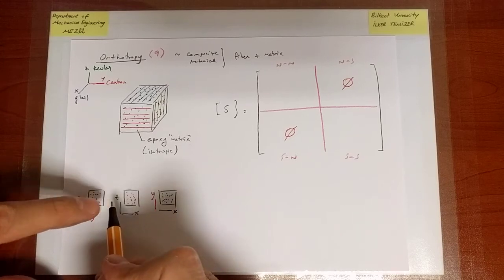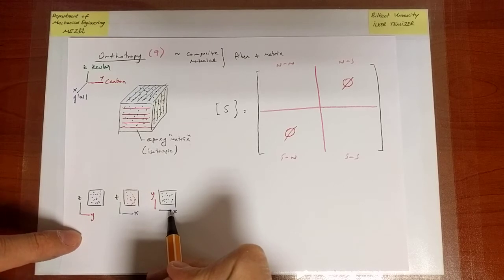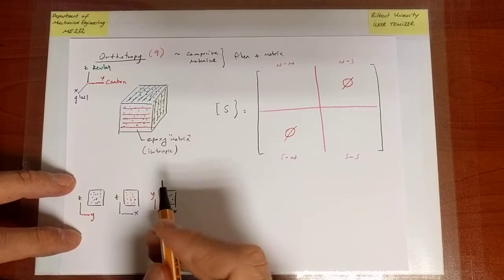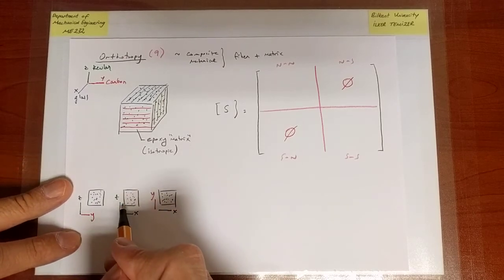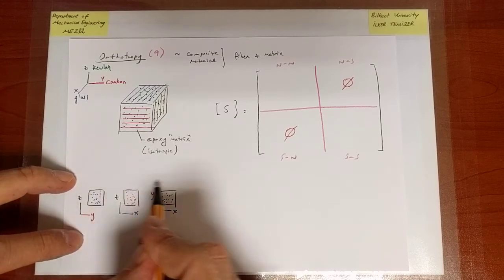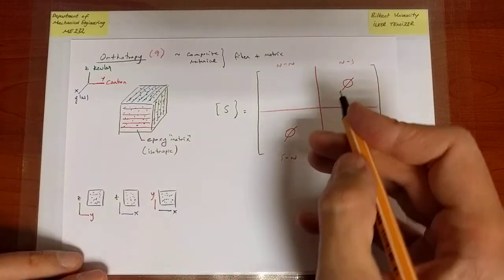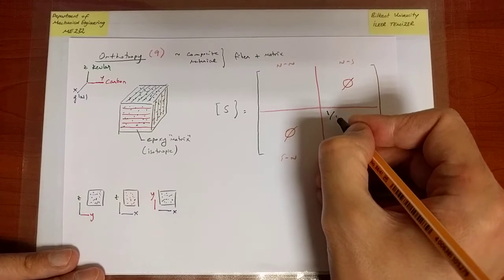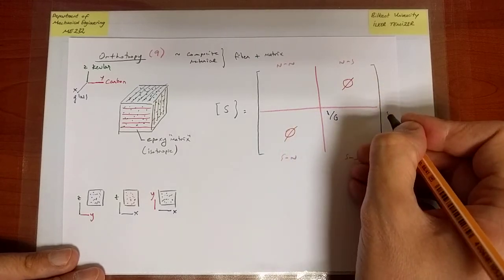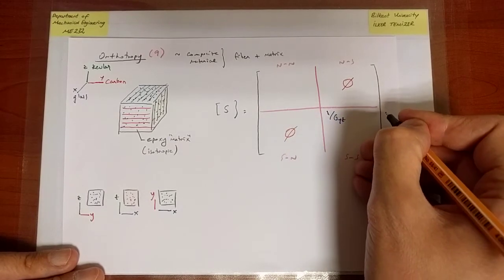Out of plane direction is also different. Here it's glass, here it's carbon. And in that case as well, it's still yet another combination of fibers. Here we have carbon and glass. Out of plane direction is Kevlar. So if I shear these two directions, it's going to be different again from this one as well. So each shearing will have to do with its own set of shear moduli. So remembering the order, this one is going to be a shear modulus that sends a shear stress to a shear strain. And so it is YZ, that's the first one appearing.